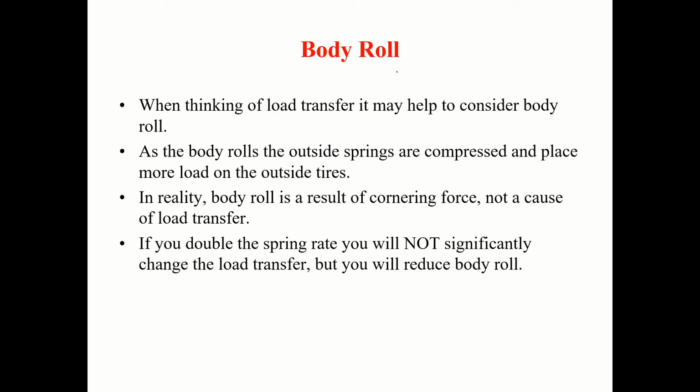So now, body roll. When thinking of load transfer, it may help to consider body roll. As the body rolls, the outside springs are compressed and place more load on the outside tires. So we have studied this. If you have a spring mass like this, and these are the suspension springs.